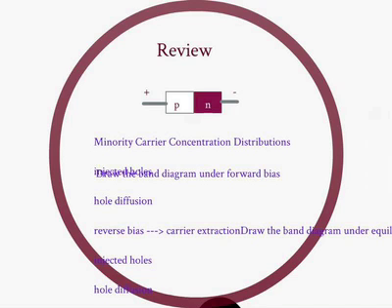Okay, so the p-n junction: the valence band and conduction band for the p-type, the Fermi level is up here. For the n-type, the Fermi level is down here. Your band is just like that, right? That's under equilibrium. What happens when you apply forward bias? This is the starting point, not the solution yet. The bands come together. Yes, exactly.